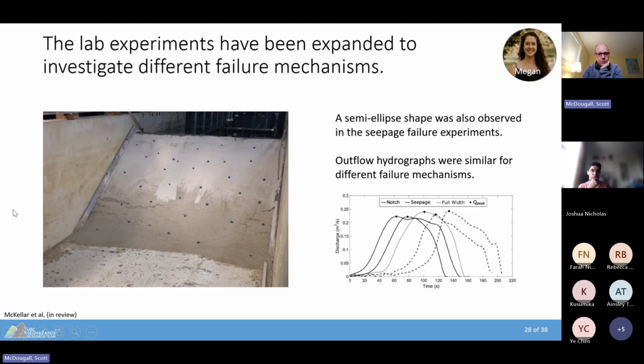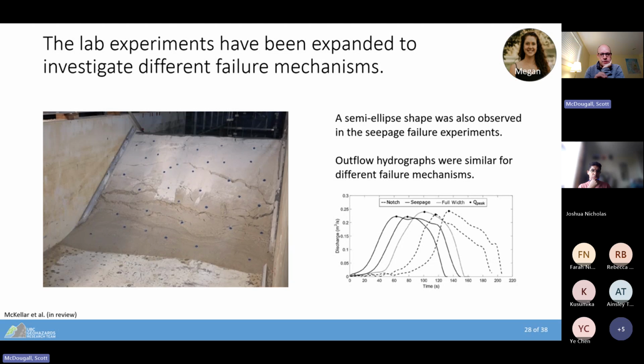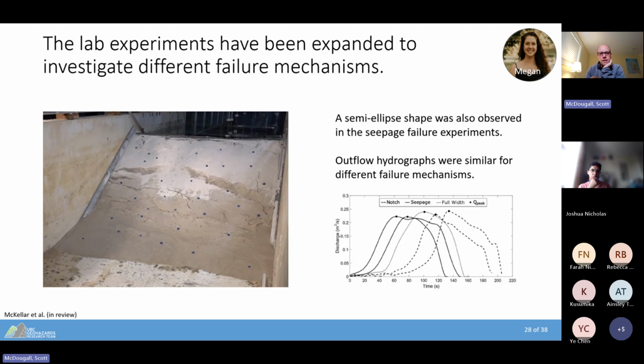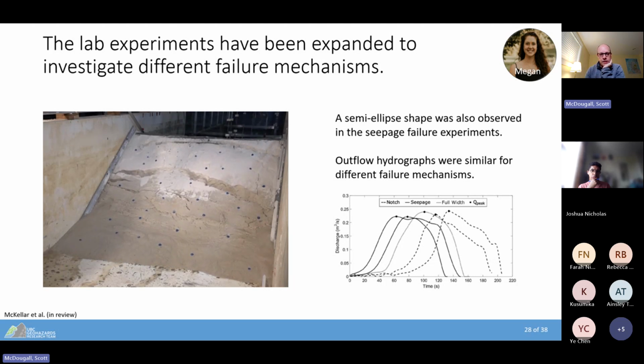You can see it's instrumented with pore pressure sensors. She's cut off the drainage at the toe of the dam to try to increase the saturation of the material in the dam and induce this landslide essentially, which lowers the crest of the dam and induces the overtopping, the catastrophic overtopping that you see at the end of the video.